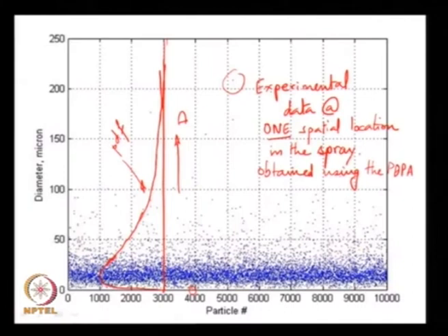So, for example, I could have more drops at another point. That would give me 2 peaks on the drop size distribution, which would be perfectly acceptable. It would just be called a bimodal distribution, and there is nothing that precludes us from having more and more maxima, but in a real spray a bimodal distribution is about as complicated as we get. Typically, a single mode, a single maximum on the PDF, is more commonly observed.